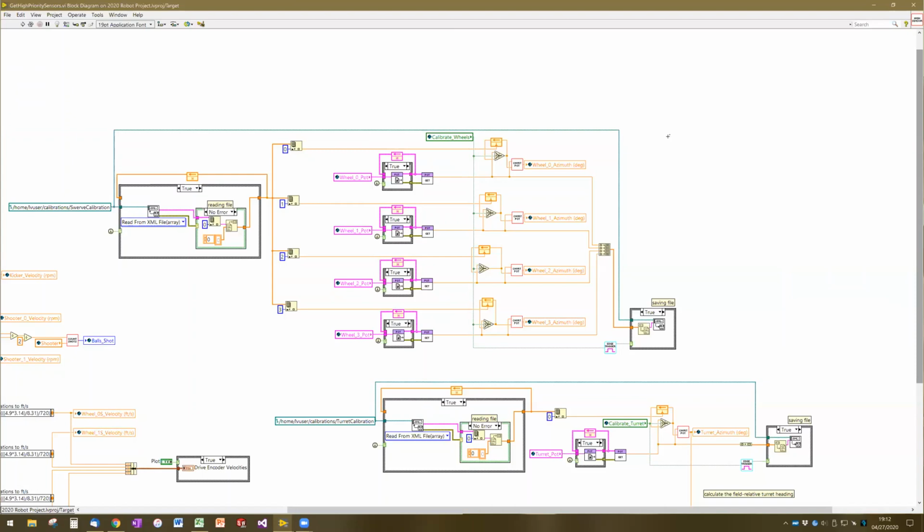I think most of you have driven the Swerve drive at least a little bit. Some of you may not have driven it at all. Swerve drives tend to be very, very difficult to control in robot-oriented mode because you have so many different things to worry about. And particularly this year, our robot was very square and kind of symmetric, which makes it hard to see which way is forward. And so you end up having a lot better control. It's a lot easier for the driver to control the robot in field-oriented control.